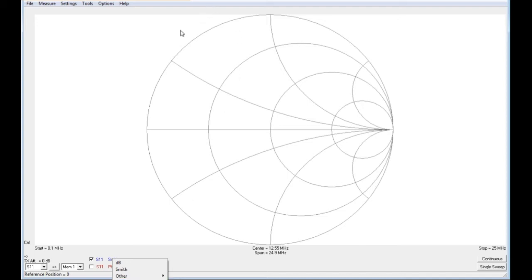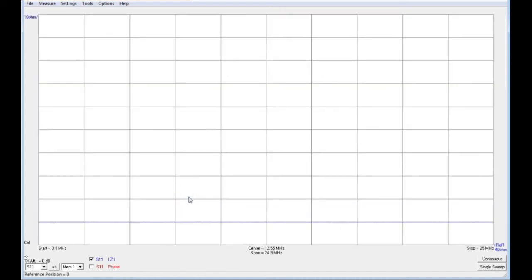I mean, the most useful for beginning, and that I use, is to show the magnitude of the impedance Z and also the phase of that. So if I come down back here, I'm going to select there. I'm going to go into impedances, slightly off the bottom, and I'm going to select the magnitude of Z, and that brings me back to here.